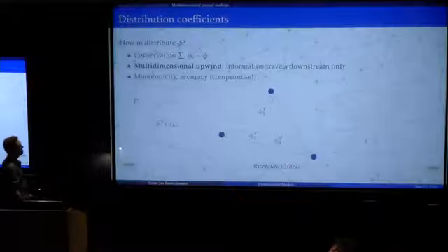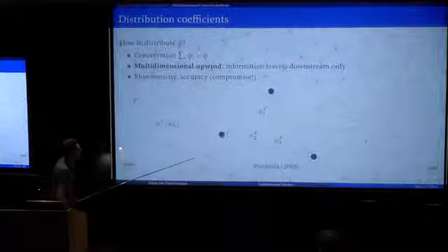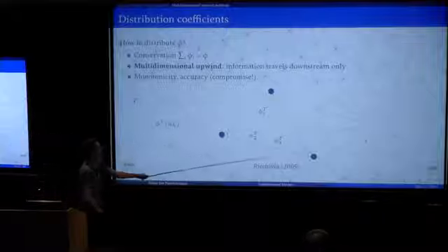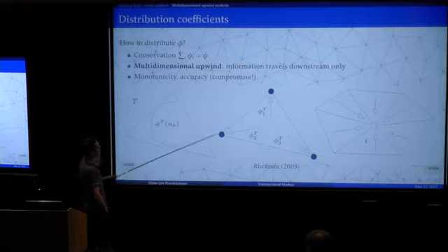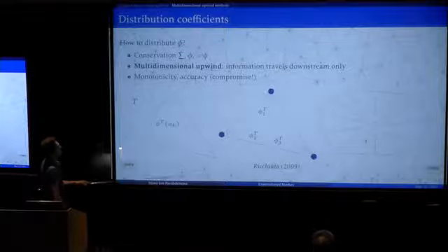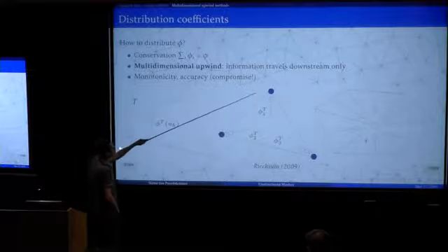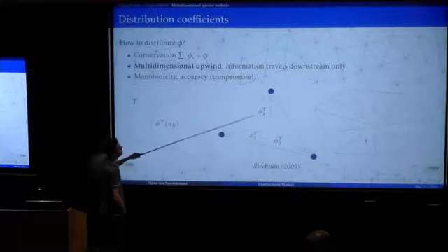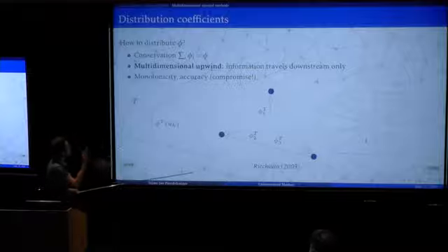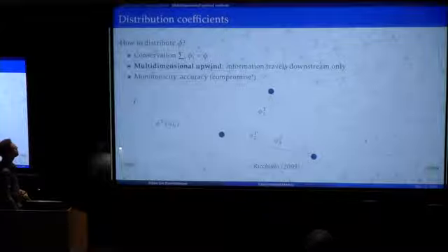But a very important design criterion is that we can take into account the multidimensional nature of the flow, because we have this, in this case, two-dimensional control volume that we can use to make sure, for example, that information in a hyperbolic problem only travels downstream. We can take into account the multidimensional flow, unlike in, for example, a dimensionally split method.